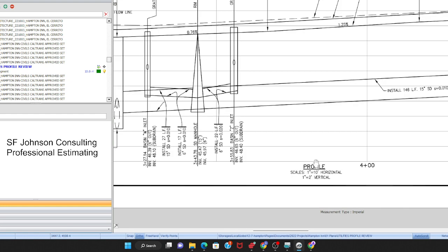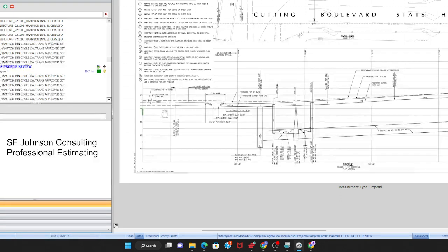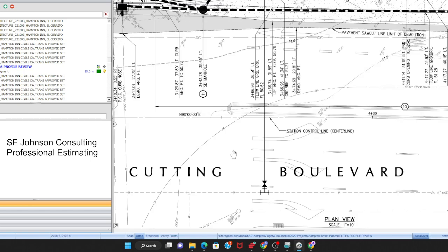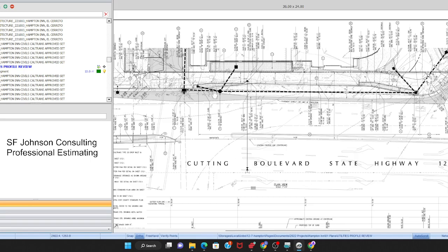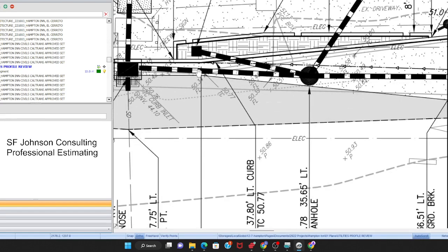So if you have a profile view of the earth, you can use the scale here to give you an area. That's 2 dimensions. And for your third, you say, well, it's going to be built here. I'm going to give my third dimension a foot on that side, a foot on this side, which is 2 feet. So that's your third dimension. And then divide by 27, because at that point you'll have what? Cubic feet. Right? But you need cubic yards.